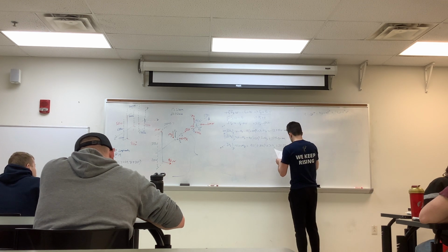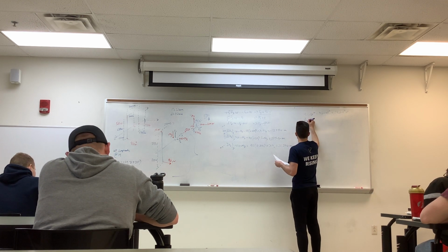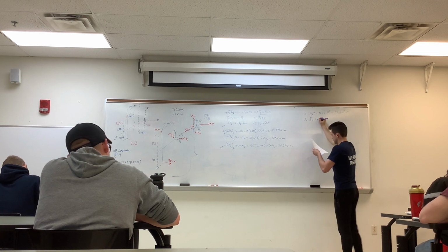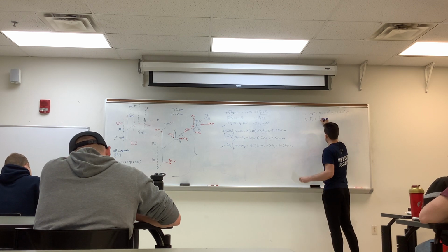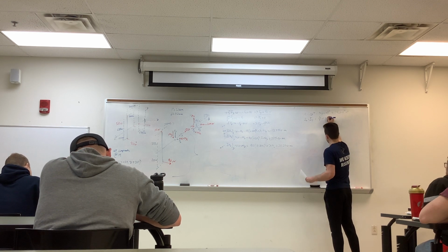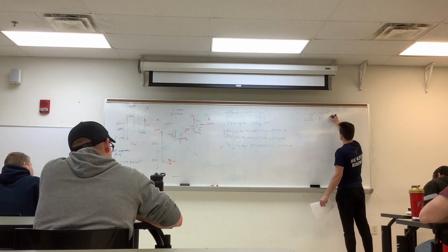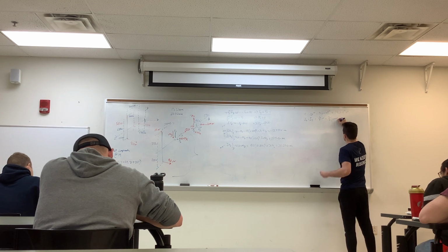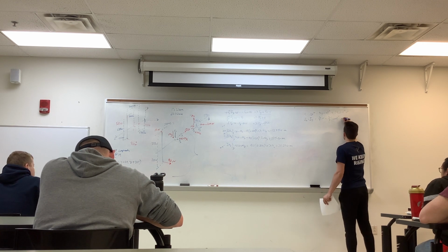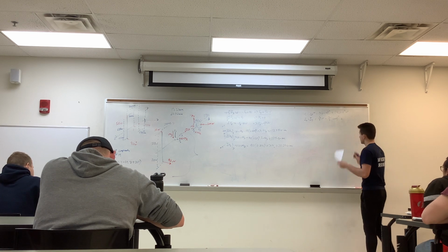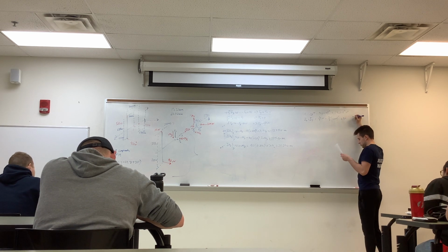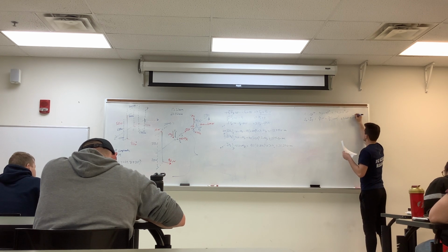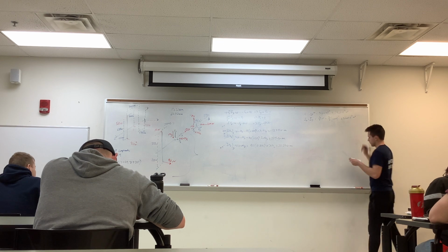I sub x, since it's a circle, it's also equal to I sub y, which is just pi over 4 r to the 4th. And that is just pi over 4, the radius, which is 0.025 meters to the 4th. We get that to be 3.068 times 10 to the negative 7th meters to the 4th.